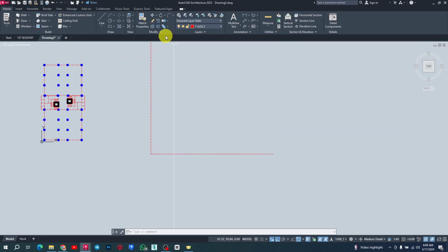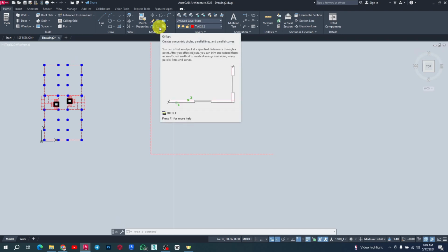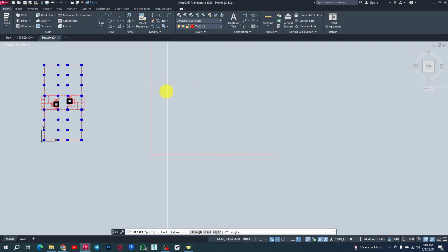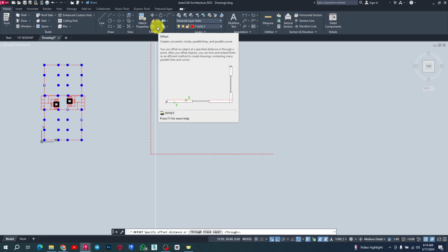I want to start offsetting this line. So I'm showing you just what I use and what works for me. I'm going to go to offset. My first dimension here was 7 meters. I usually want to include the thickness of my wall, because I draw using center line. So if this is a center line, you want to include the thickness of your wall to that line. In Cameroon, the main block that we use for construction for elevation is 150 mm.